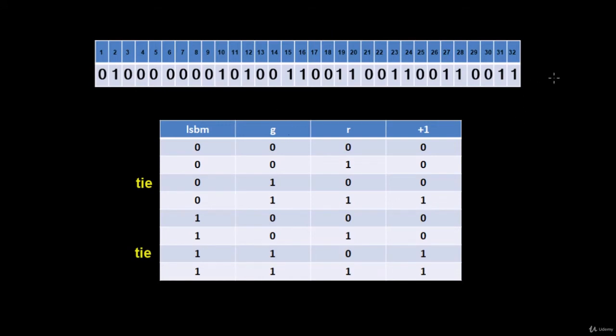The very next set of bits after that are the sticky bits. What we do is we OR those sticky bits together. If the value of the OR is 1, then we set the rounding to a value of 1. If the value of the ORing of these sticky bits is 0, then the rounding is set to a value of 0.